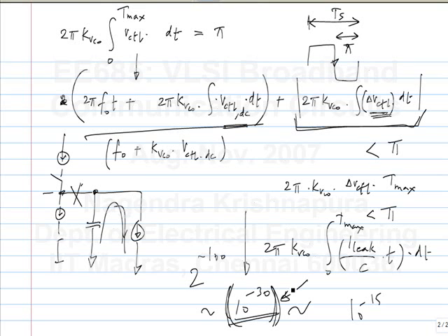Yeah, that's right. Well, to some extent, right? So there is a raw bit error rate, that is, you send these bits and you see how the bits differ. Now there can be coding and other things in it which will let you correct it even if there is some raw bit error rate. That is, the net bit error rate is much better than the raw bit error rate.